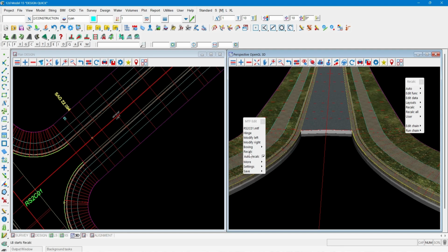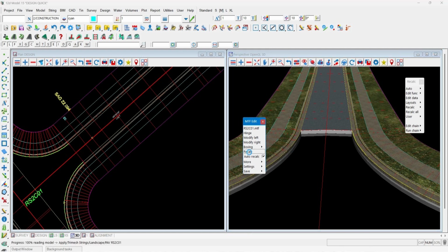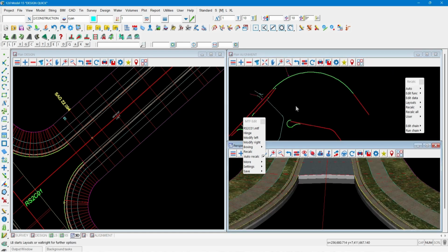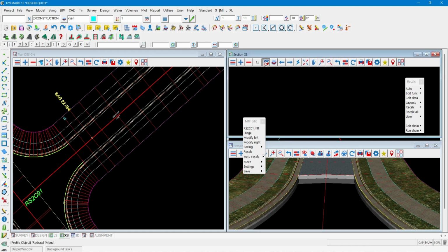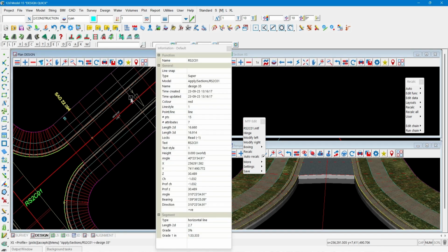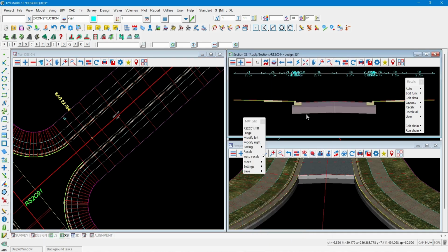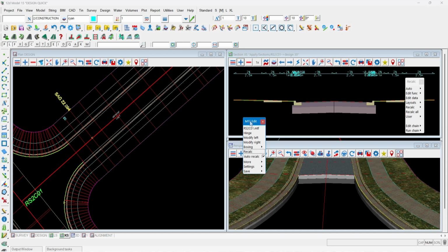And because that snippet directly responds to the pavement types, if I recalc that design, you'll see that that bottom pavement is going to get actually thicker than what it was. And this will also be easier to explain if I pull up a cross-section view, and we'll profile one of those design sections, and we'll add the tri-mesh pavement models. Okay, so those are those tri-meshes that have been applied within the MTF file itself. So that's coming directly from the seed file, and inside the seed file it has our inbuilt snippets, but they can have your own snippets in there.